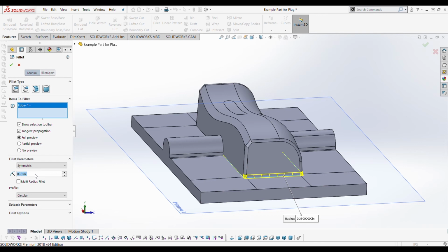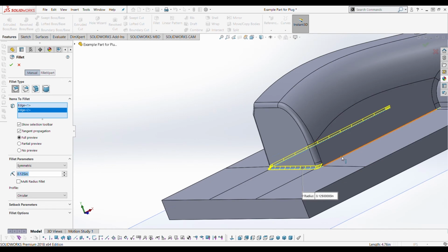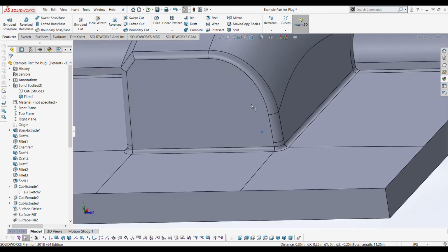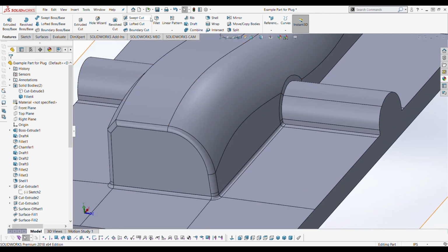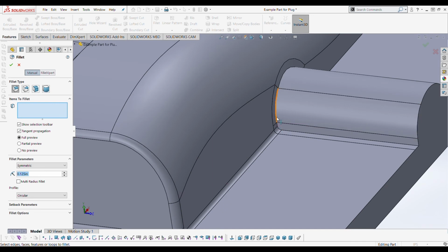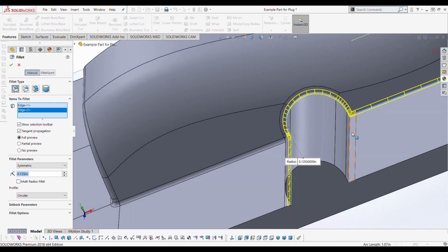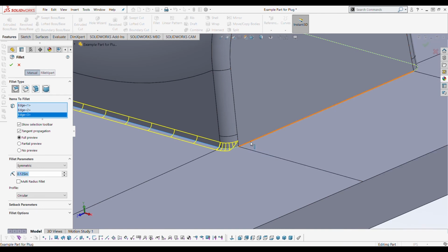And so knowing that we use a 1/4 inch ball end mill for finishing, this is going to be 1/8 of an inch all the way around, which once again we can confirm that our part will not be lost because of the fillet along the bottom edge. And you don't actually want to have sharp 90-degree angles anyways, so having that fillet there is going to be better in the long run as well. So we could go ahead and continue putting these fillets in all the way around our part if we'd like, just to imitate what it's going to be like once we do machine this mold, or this plug, excuse me.